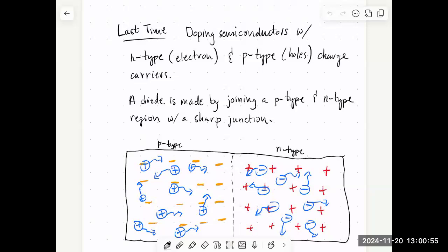So we decided to replace the occasional silicon atom with an impurity or a dopant, one specially selected to have one extra valence electron, and that was called N-type doping. In that case, 4 of the valence electrons would be in covalent bonds, but there would be a 5th one left over, which could detach from its host atom and move throughout the material.